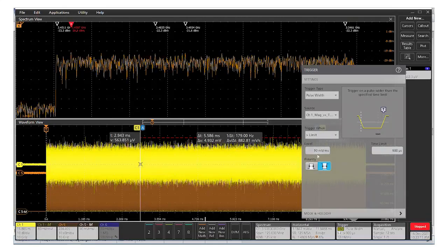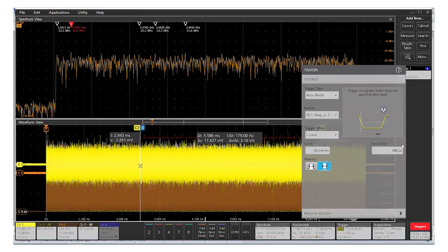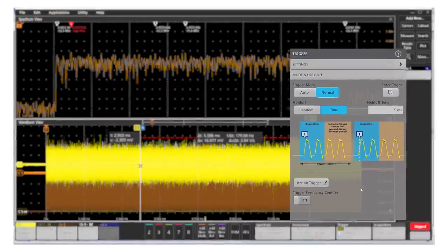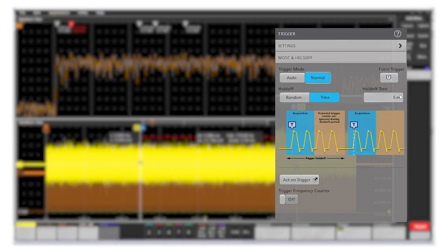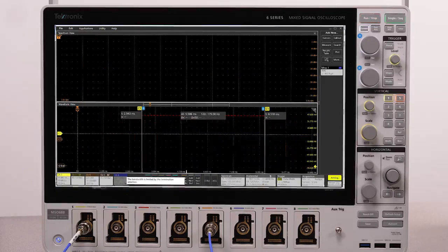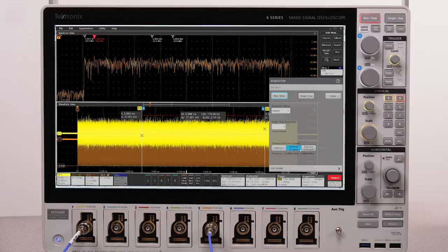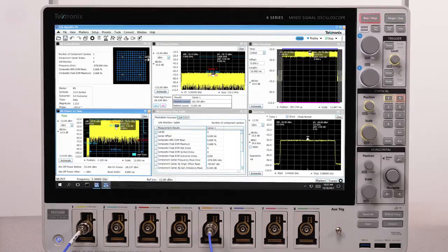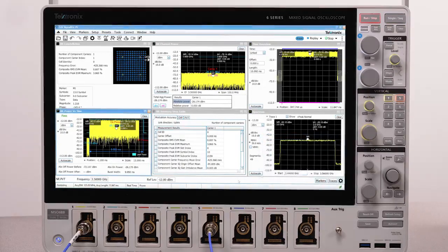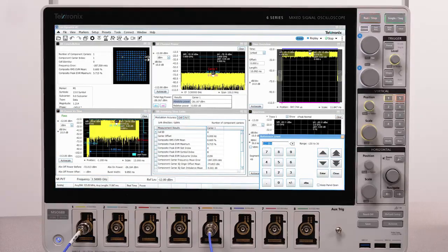And we've specified the height of the pulse to be 10 millivolts RMS, and we've specified a time limit of 900 microseconds. We're also using hold off to not trigger too quickly, which is about half of the typical 5G pulse of 10 milliseconds. Next, we've set the acquisition settings to use the external frequency reference to set the time base accuracy. Now we'll go to SignalView to set the center frequency and the reference level. The scope generates the IQ data that SignalView can process and analyze.